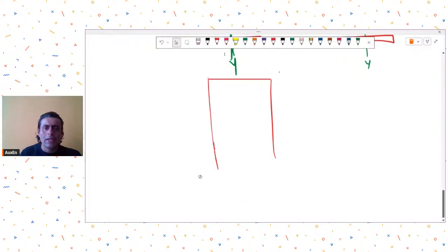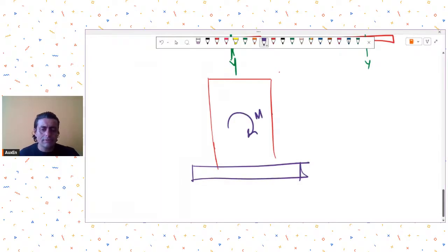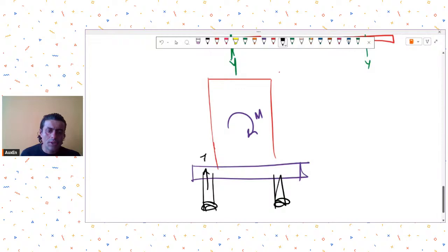So when you provide a pile cap and piles, it is very easy because of the large moment you have. In the form of piles you have elements to resist the tension due to the generated moments. So providing piles below your shear walls is a good option, because you have introduced an element which can take the tension generated due to that moment in the wall.